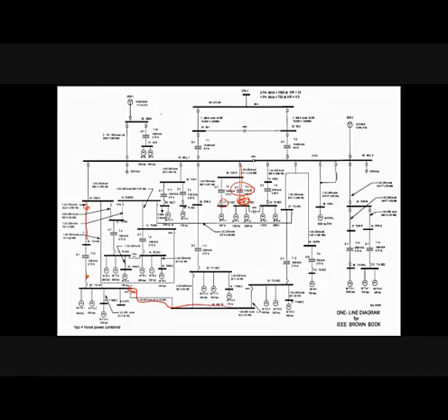Power can come from this line, and at the same time, power can come from this bus bar. If this line is connected, what happens to the current flow from this line? Is this current flow still within limits or not? If not within limits, we have to isolate these loads. We have to disconnect this line also.